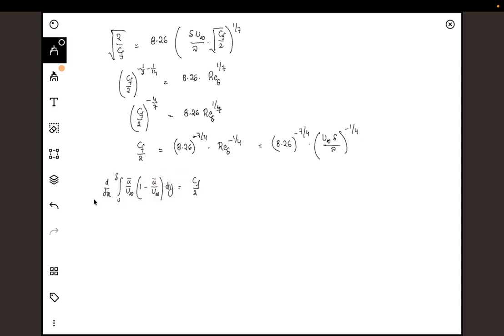So this is my equation 1, this is my equation 2, and I have my third equation that u bar by u infinite is y by delta to the power 1 by 7. As you can see, this particular form will only satisfy the no slip condition at the wall and the free stream condition. Only these two conditions will be satisfied with this particular form. It doesn't have anything to do with the gradients. Which is exactly why we need the universal turbulent velocity profile to be able to solve this.